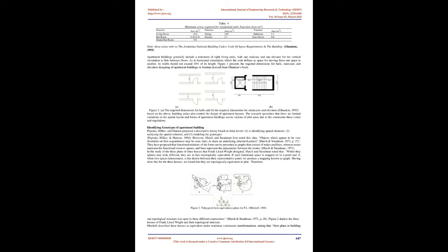However, it should be noted that the area of the duct, the interior space within the construction limits opened and exposed to the outside air to deliver lighting and ventilation to the rooms overlooking the duct, is excluded from the total area of the apartment plan if its area and length are equal to or less than regulation requirements. Table 3 depicts the regulation for ducts in apartment buildings.